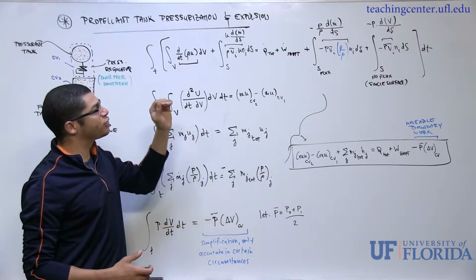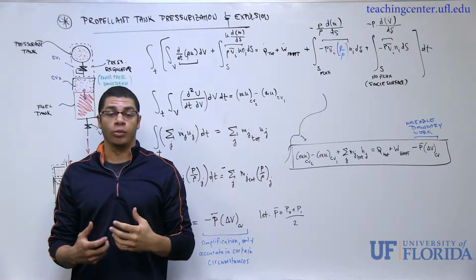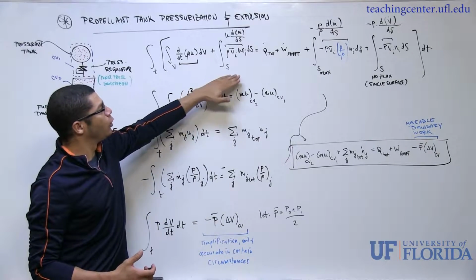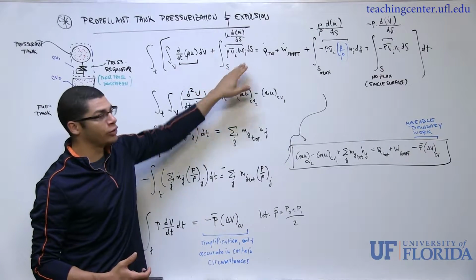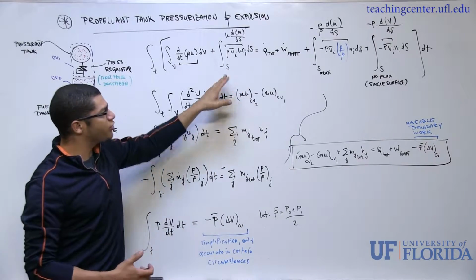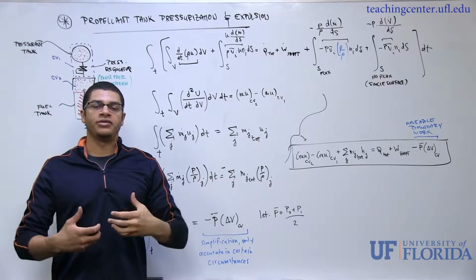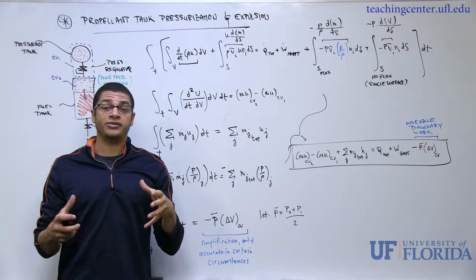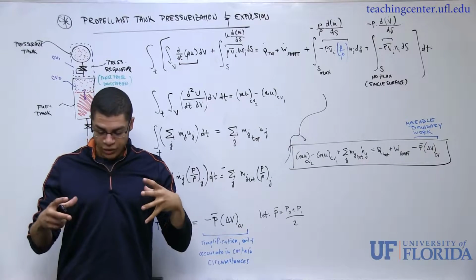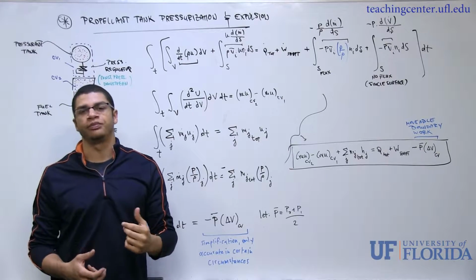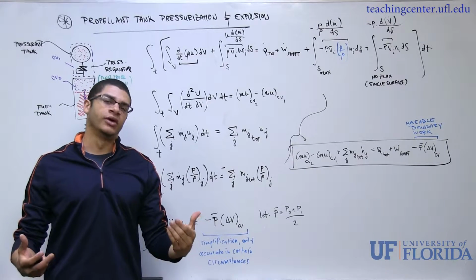But since we're going to have some flow into or possibly out of our control volume for this example, we want to use this approach here, where it allows us to express our flows into and out of the system as an internal energy flux. But just to be clear, the previous formulation where we only had one term on this side is typically used when we have either a fixed volume or a fixed mass of particles that we're following around. It's called the Lagrangian approach.